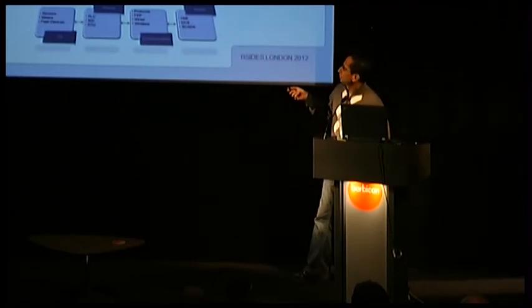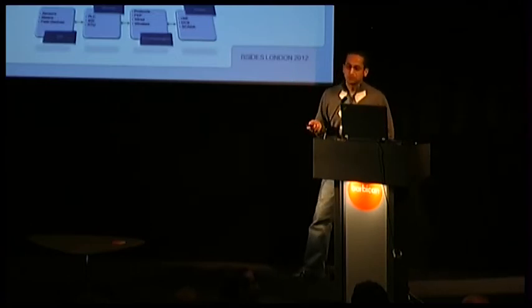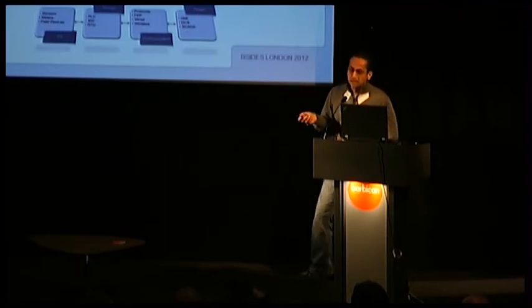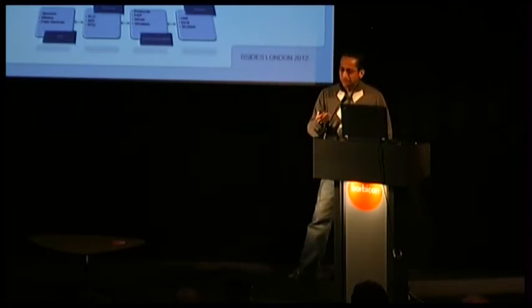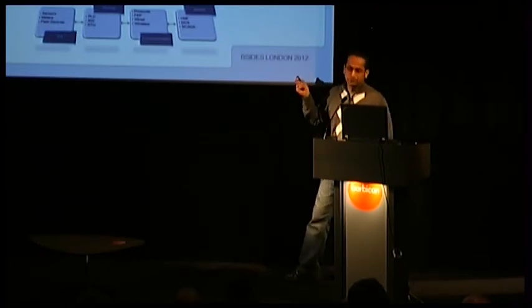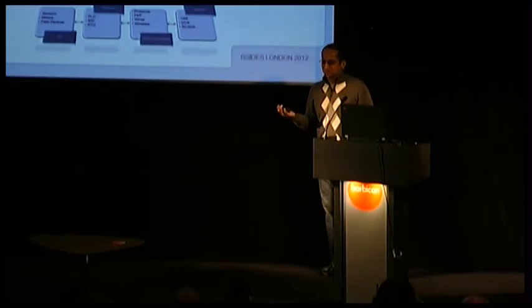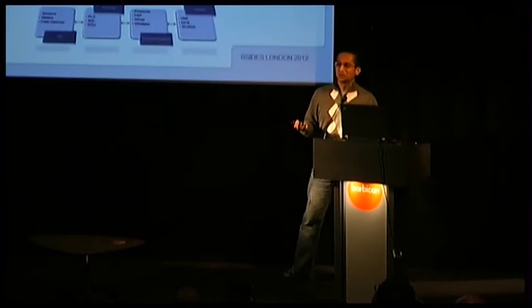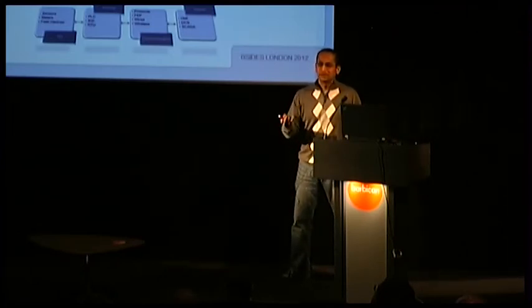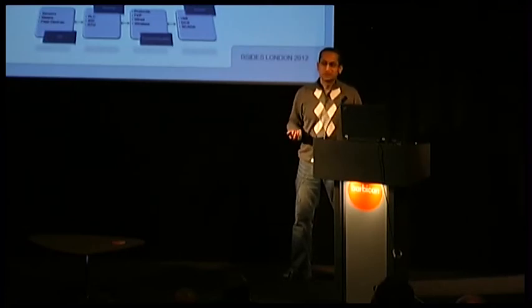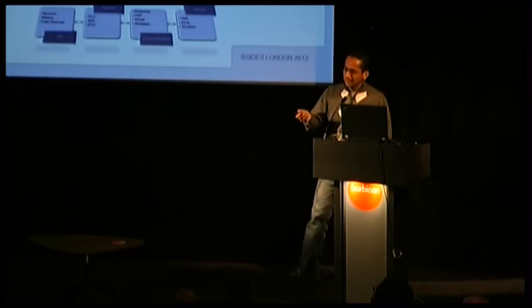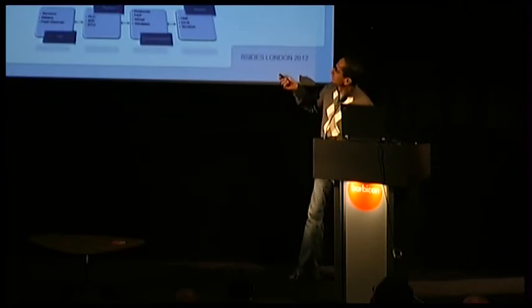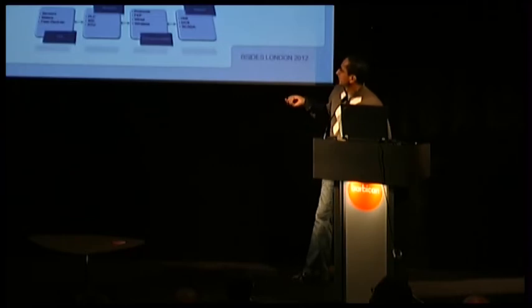And then these measures use one of the communication mechanisms to transfer all that data to the control center. Now, communication can be wired, wireless, using radio, any of the communication mediums, and it uses one of the SCADA protocols that I have mentioned here. It's said that there are about 100 different SCADA protocols. I've not been able to count all 100 of them, but I can definitely at least list 24 protocols if someone asks me, hey, tell me some SCADA protocols. Some famous protocols are Modbus, ICCP, DNP3. Basically, their function is to communicate the data from this component to the final component, which is the SCADA master.